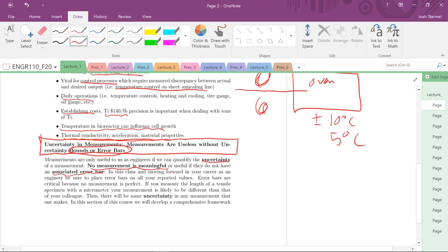It's important too, because if you're designing a material or an application, and you just state that it's this value, for example, that the UTS, the ultimate tensile strength, of titanium is 100 megapascals. It's not. And you give me that value, and I design my application thinking it's exactly that value, but you failed to mention that when you measured it, it was 100 megapascals plus or minus 50.